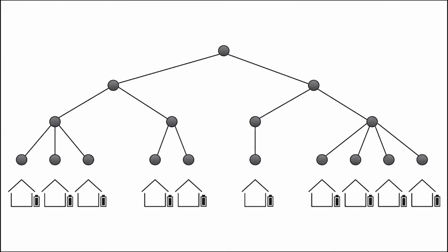And a typical way to do this is through hierarchical aggregations, where the hierarchy is a virtual representation in cloud software. The first level is that digital twin that I mentioned earlier, representing an individual site. So that's a house with a battery. And the next level might be organized by electrical topology, like a substation, or by geography, like a county. And then the next level can again be a physical grouping, like an electrical interconnection, or it might be logical, like sites with a battery and solar, and sites with only a battery that we want to model or control differently. And these sites come together to form the top level aggregate of the virtual power plant. And this means that we can query an aggregation of thousands of batteries as fast as we can query a single battery, and then use this to inform a global optimization.